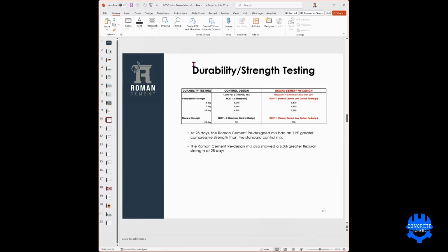What I would propose that a cement company could do would be to create a one-piece cement where they intergrind cement and pozzolan, and maybe they could grind it finer than usual. Even though it's going to be finer, they can then backfill it, like John said, without intergrinding with the raw kiln feed, which is typically a lot coarser than the cement clinker is ground. It is around the 80 to 120 micron size, as I did some research.